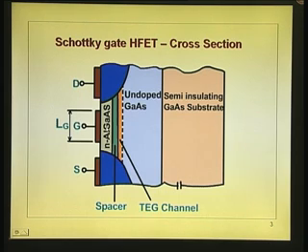Gallium arsenide layer will be depleted due to two reasons. One, due to the gate depletion layer, other one due to charge transfer from the AlGaAs to the gallium arsenide. So, the depletion layer here is the result of two junctions playing on that AlGaAs layer. One is this p-n junction, other one is Schottky junction.